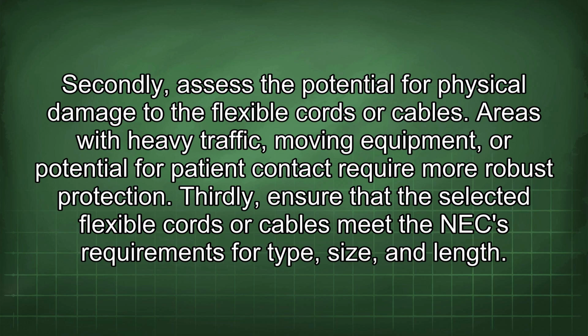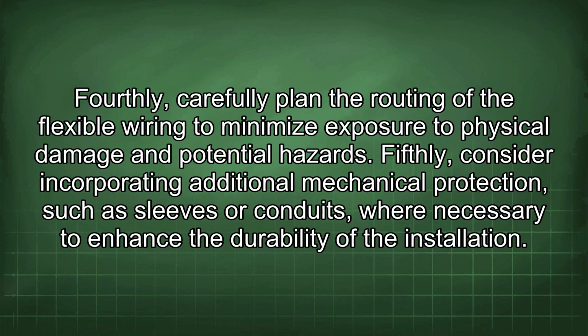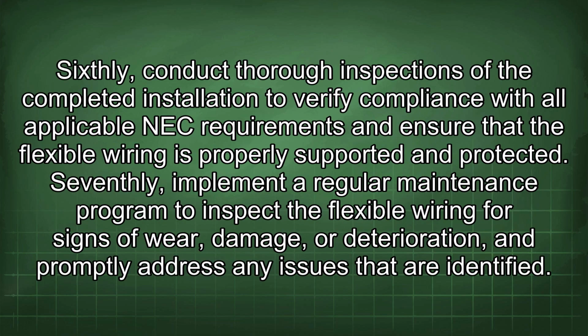Thirdly, ensure that the selected flexible cords or cables meet the NEC requirements for type, size, and length. Fourthly, carefully plan the routing of the flexible wiring to minimize exposure to physical damage and potential hazards. Fifthly, consider incorporating additional mechanical protection, such as sleeves or conduits, where necessary to enhance the durability of the installation. Sixthly, conduct thorough inspections of the completed installation to verify compliance with all applicable NEC requirements and ensure that the flexible wiring is properly supported and protected.